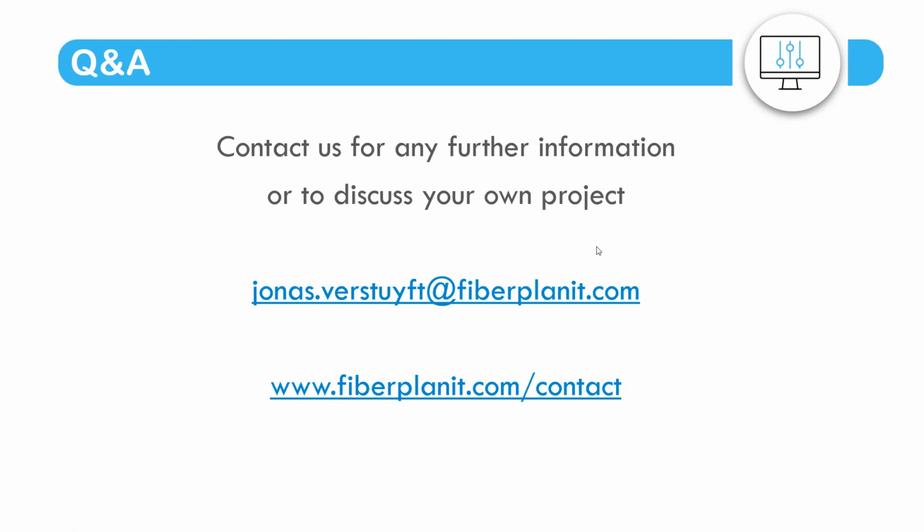Another question I see here: does it provide a conversion from single line to multi-lines? Indeed, that is an option. So for the plans that you want to generate, if you need multi-line plans, there's functionality to create those multi-line plans. I think in the examples that I showed, those were all single-line plans with the labels indicating that there are multiple cables in the same trench. But for visualization needs, you can generate multi-line plans as well.